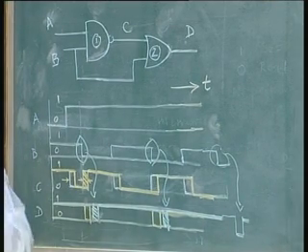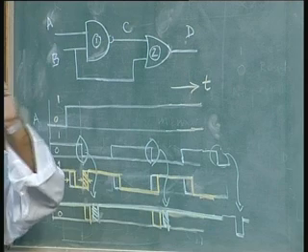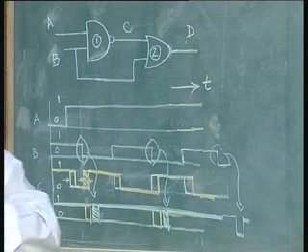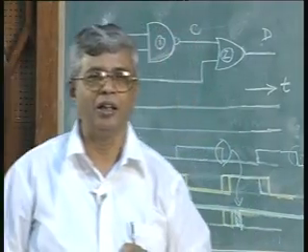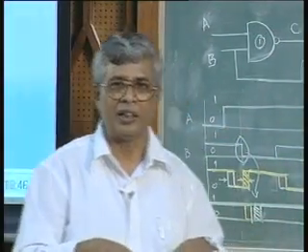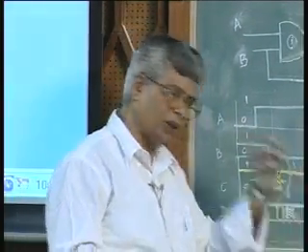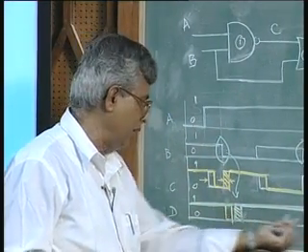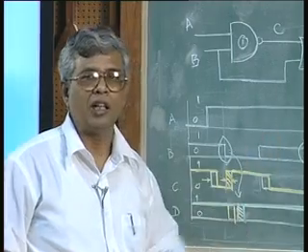The flip flop operation is because of, remember that RS latch we started with, the 2 inverted NOR gates. That should be the one to which the input is considered. All other things are only external peripheral circuitry. So, to that input circuit, the input will change only very narrowly like this. So, this is how an edge triggered operation comes.